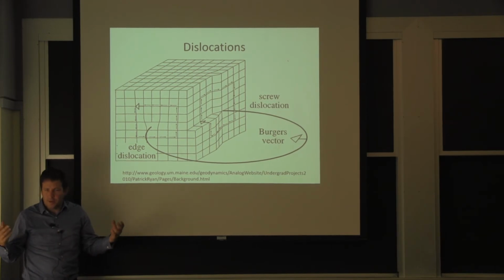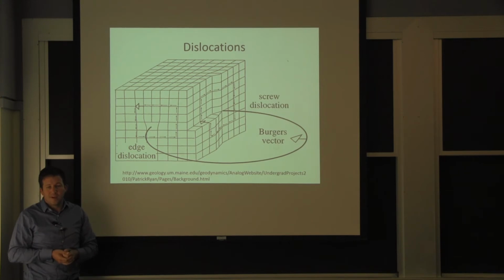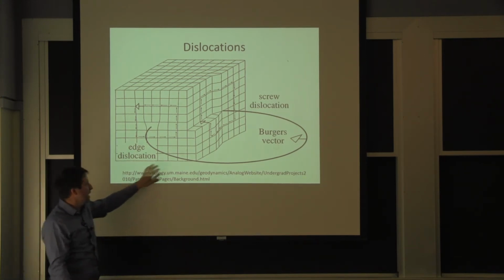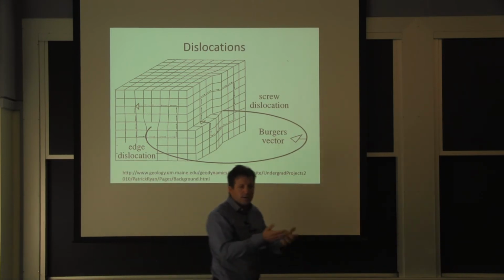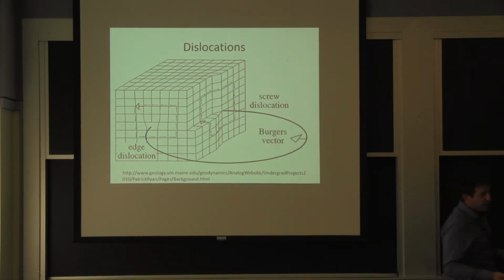When they come from different directions and hit each other, that's where you form elements of resistance. There's very little resistance associated with just making the dislocations in metals. If you're looking at ceramics, it's a completely different story.